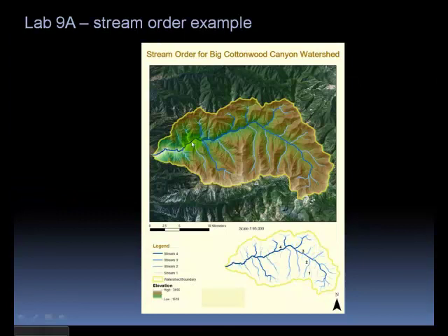When you're done with your threshold, you've got your binary raster, you're going to want to assign no data so that you're only dealing with the channel network. Then you'll be calculating Strahler stream order from the flow accumulation channel network that you have. And when you're done, you're going to want to convert that channel to polylines so that you can actually display it in an effective way. The raster cells really don't display well, but by converting it to polyline, you'll be able to use the stream orders to assign different colors and line weights.